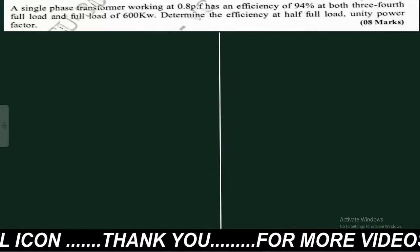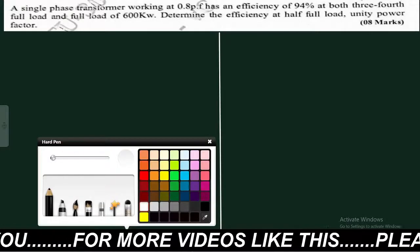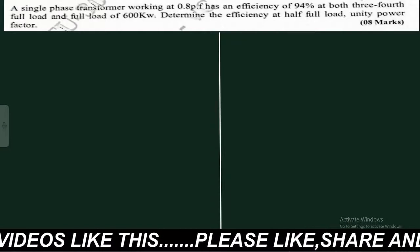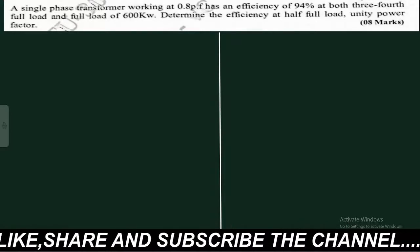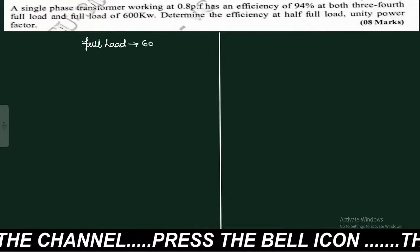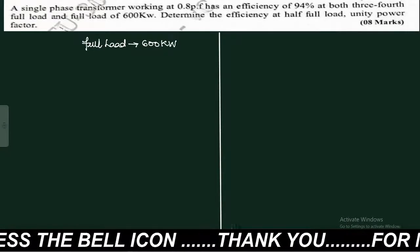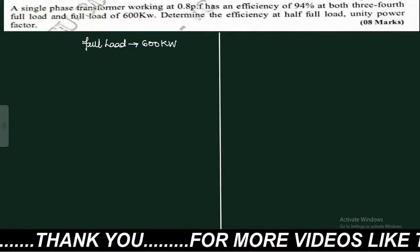This is somewhat different question, so the first step is somewhat different. If you read the entire question, you don't have the rating of the transformer. So first of all you have to find the rating of the transformer. The full load of the transformer is given as 600 kilowatts. Normally the rating of the transformer is in kVA, but here it is given in kilowatts. The rating which is given is load.